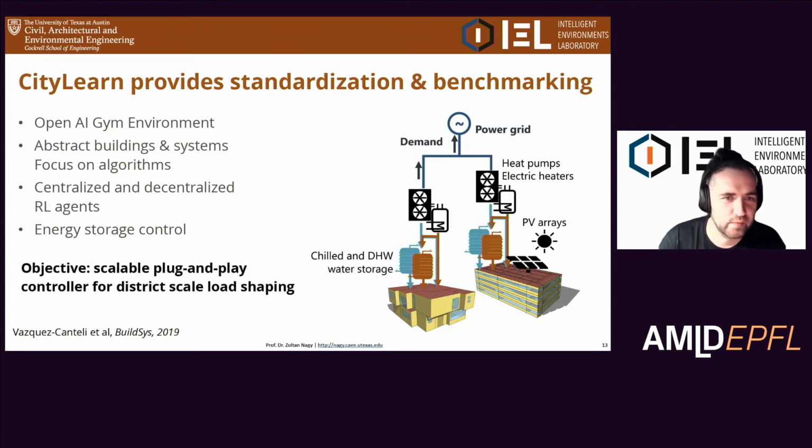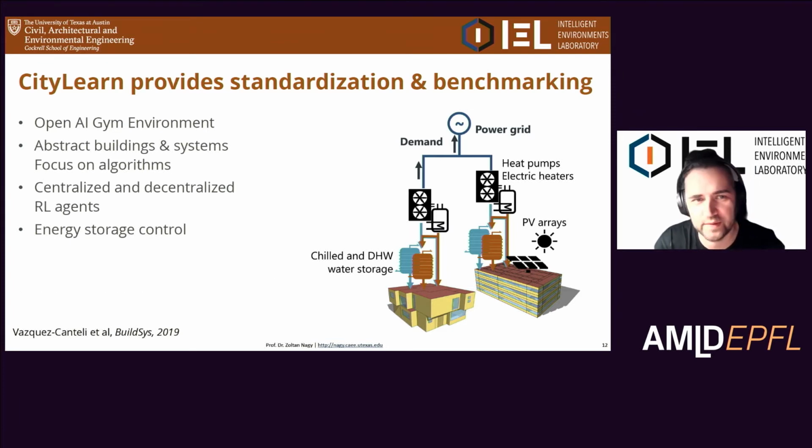What is mentioned here is you abstract out the buildings, you don't need to worry about them, and you can study all kinds of different problems, right? The centralized problems where you have one controller that knows everything, kind of like an aggregator, or completely decentralized agents, just to see what's going on if you don't do anything. But at the end of the day, what we do is energy storage control, like when do you charge and when do you discharge your chilled water and your domestic hot water and your batteries or your EVs. And you try to do that in a way that on the aggregated scale, it's beneficial to the grid.